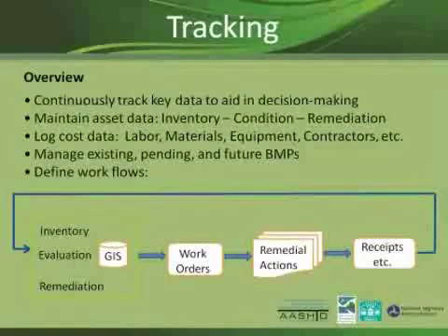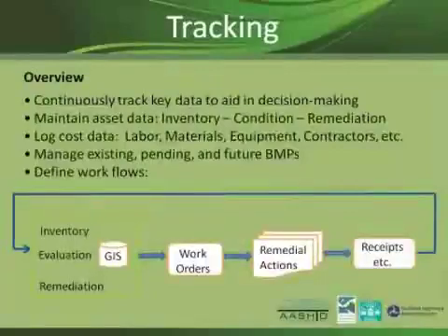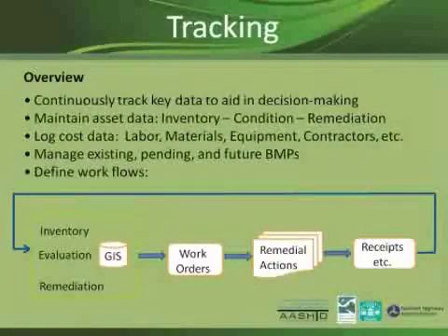Then you're managing not only existing BMPs, but preparing for pending ones and planning out future ones. And I can stress that our inspection program is really teaching us how to design better future BMPs when it comes to operations and maintenance. This is just a very simplistic workflow. Collecting all the data is just the start, but then you get work orders and assign them. For us, we look at our maintenance staff, we have contractors, and we have other vehicles for getting people to do the work. Then keeping track of that, all the documentation from the remediation needs to be consolidated and brought back into the GIS. And I can't stress enough that it requires quite a bit of coordination with your operations people. Okay, next.